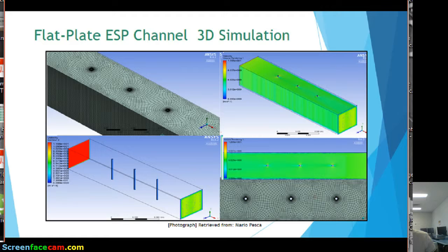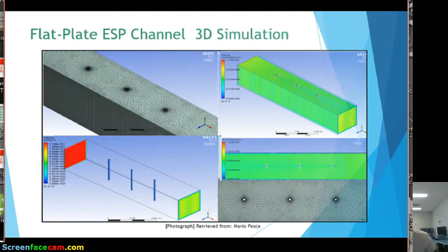So at this stage, we were already using Fluent. ESP presents multiple phase flow with transient particles, and therefore we use transient simulation in order to account for those variables changing with time. The first model was a flat plate electrostatic precipitator with a 3 electrodes configuration displaying a slight pressure drop, which was found to be a normal operating characteristic of the electrostatic precipitators.